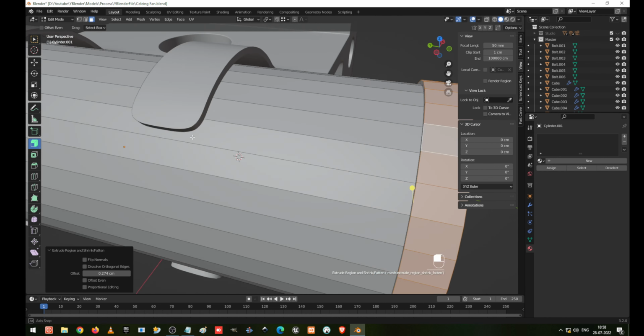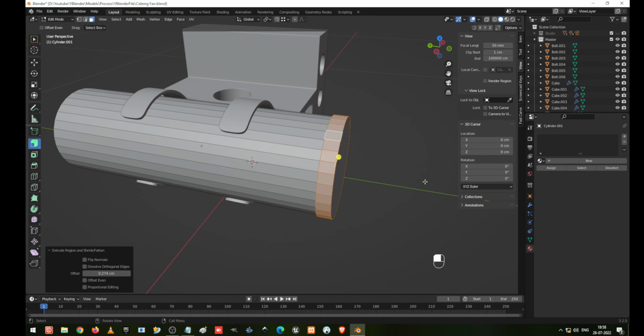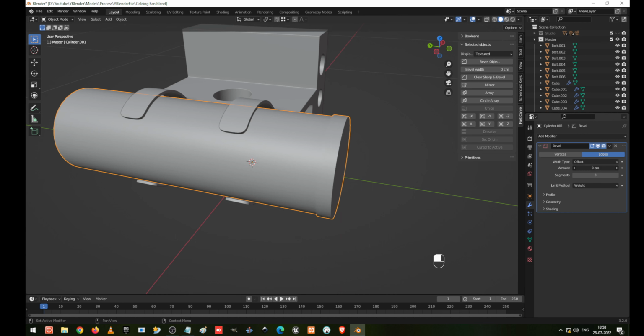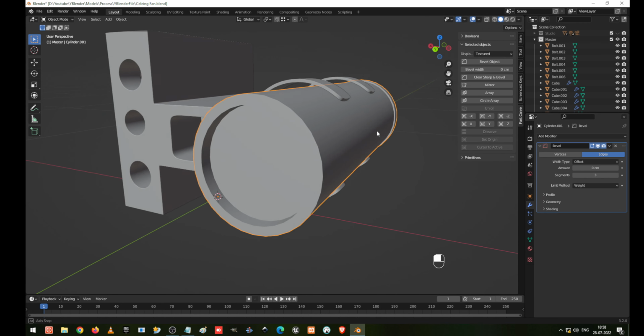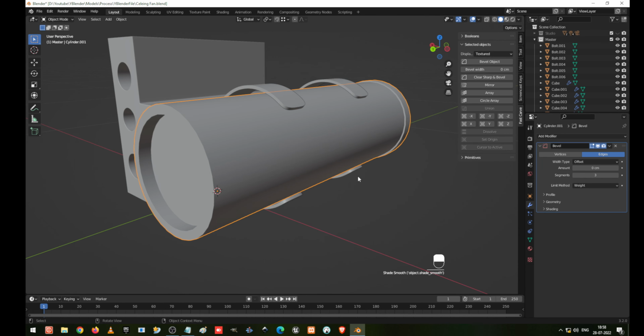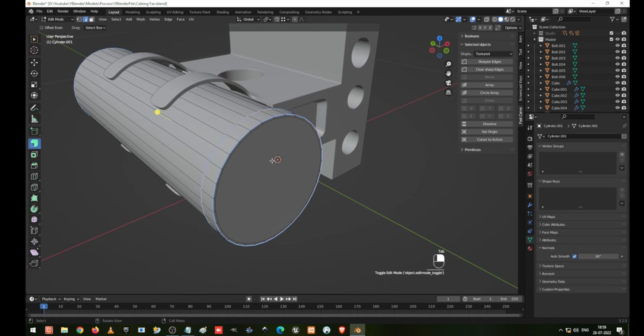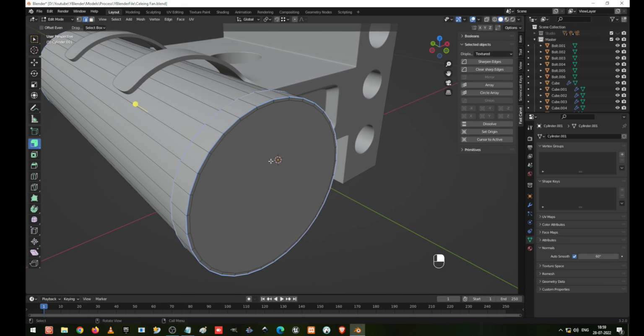I have extruded as per our requirement now, and I go to the first curve and apply a bevel, and go to the modify tool. I make it bevel 0. So now right click and shade smooth, go to this and make sure auto smooth is selected, and here we are going to do some more changes also.